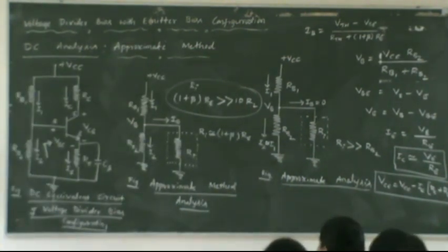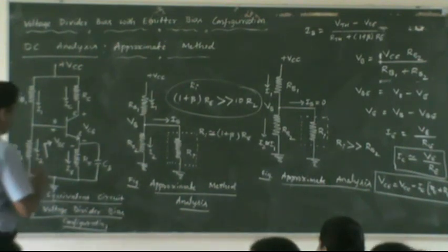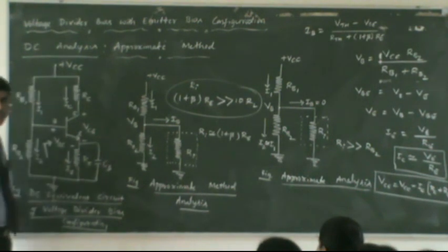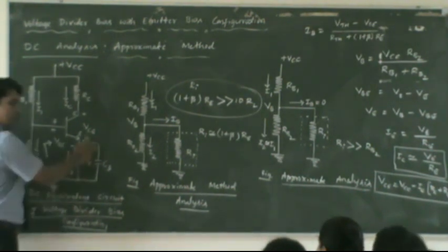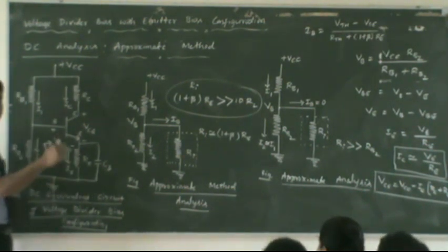You got my question now? What am I trying to say? If I add a capacitor there, anyway for DC analysis we will not use capacitors. This capacitor will be an open circuit. But look at how this behaves for AC.